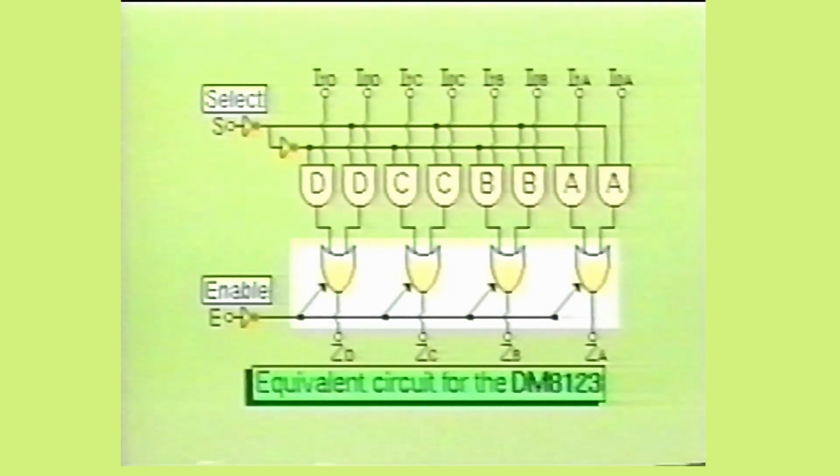The first thing you may notice about this circuit is the arrow pointing toward the body of each of the OR gates. These are special OR gate circuits which can produce a tri-state output. The output may be high, low, or placed in a high impedance state. When placed in that high impedance state, the devices are effectively removed from the circuit. The arrows may or may not be present on a diagram, but the line will always enter at the side